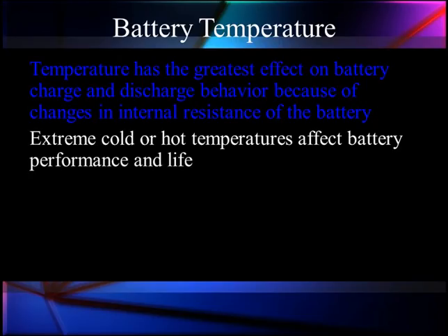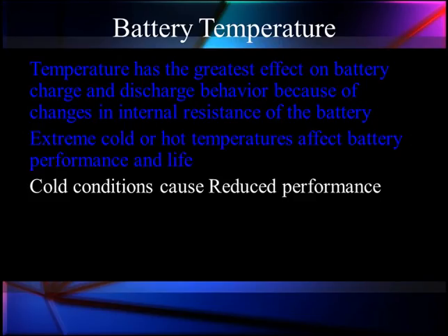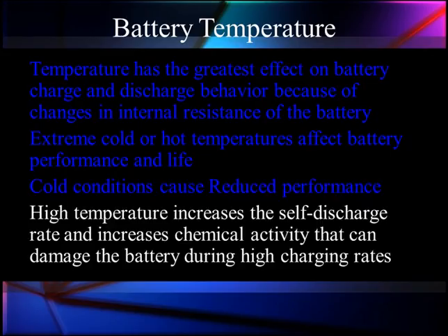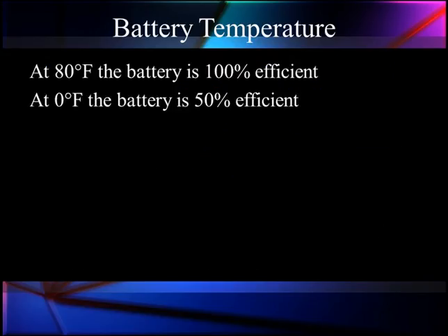Extremely cold or hot temperatures both affect the battery performance and life. Cold conditions cause reduced performance. High temperature increases the self-discharge rate and increases the chemical activity that can damage the battery during high charging rates at high temperature. Keep all that in mind.